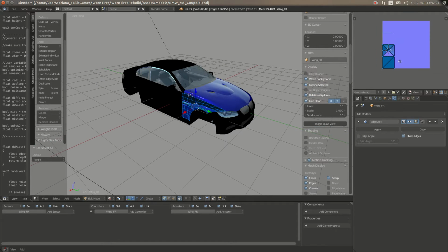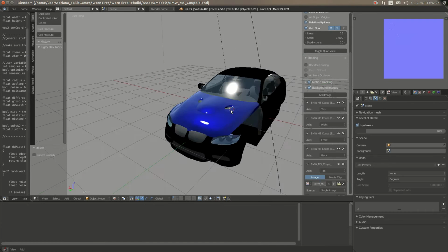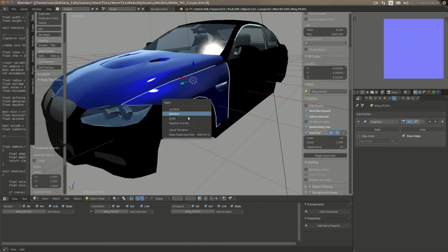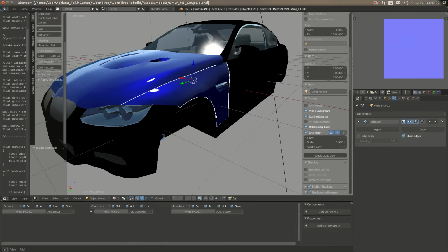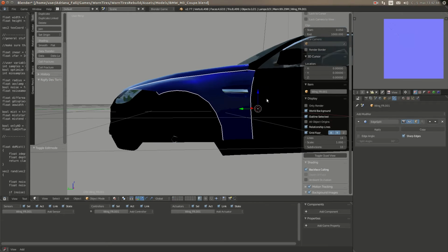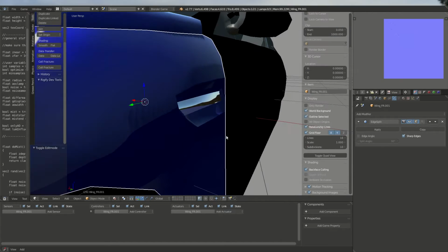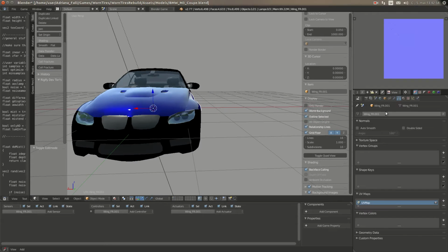We've got two objects applied here. What I'm gonna do is actually delete this and just make a copy of it. Shift D, S, X, minus 1. Control E, scale. Mesh normals, flip normals. Enable backface culling to ensure that everything works fine, and rename it wing front left.